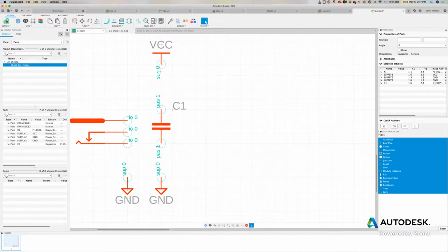It's letting me know that this is a supply pin. The characteristic of supply pins is that they're not assigned to a footprint. There's no footprint; this is only a representation of power. So I'm going to have power plugged into this jack, and that is going to be called VCC. I'm going to take this VCC and distribute it through the rest of my schematic, so I'm going to click on the net command here.